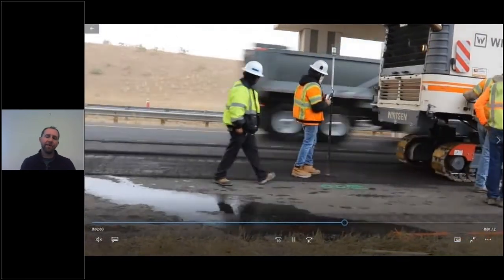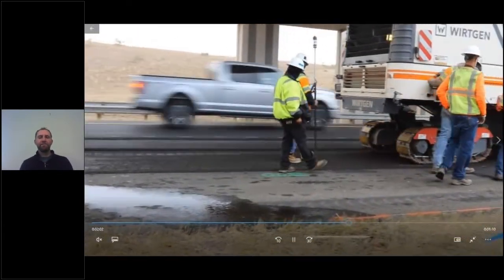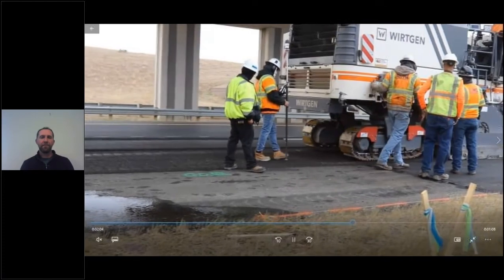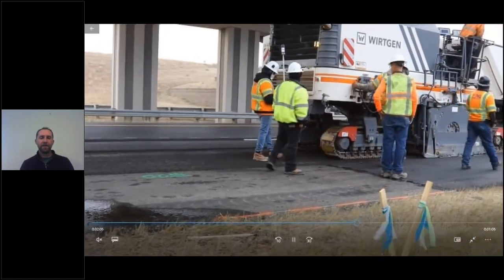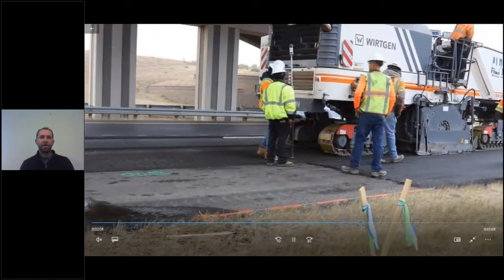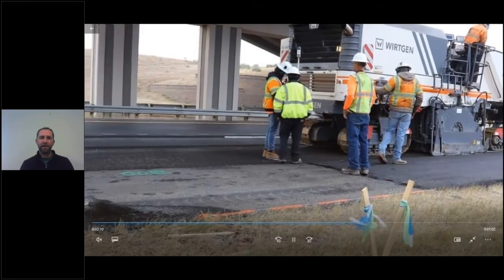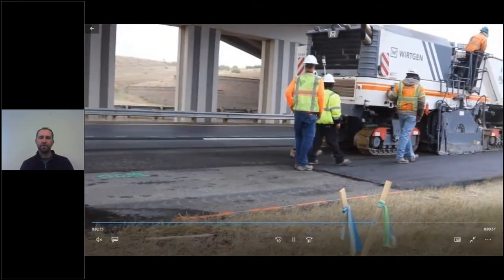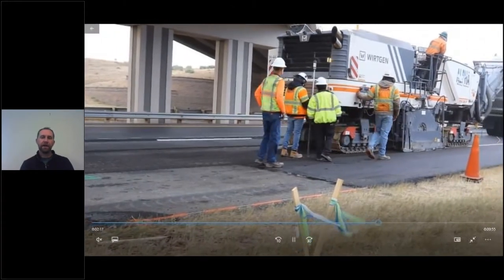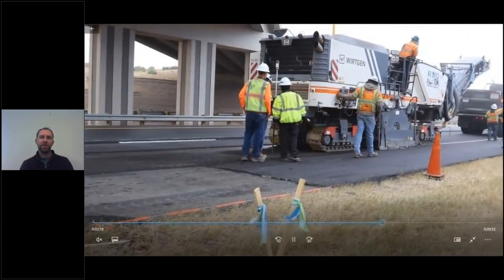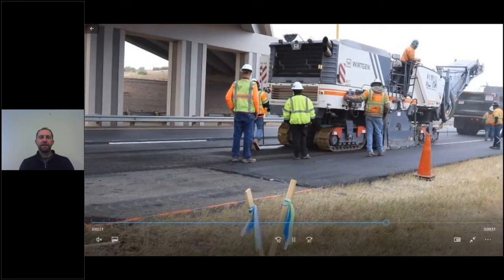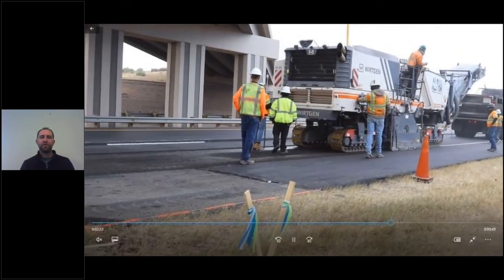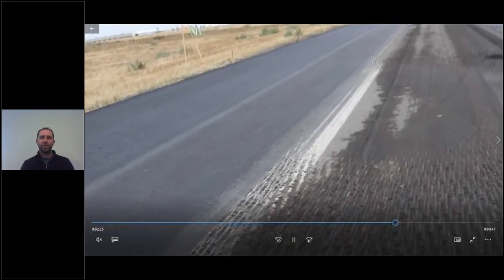Okay, there's my video that I was looking for. So that is my data collector, kind of the close-up of him. He's got a little tablet there as well. He's got the model loaded in there and he's able to check, is this point accurate? As long as it's communicating with that total station, it knows where it is. It now knows its elevation and it can tell you, is it correct? Is it a hundredth of a foot too high or 2/100ths of a foot too high?